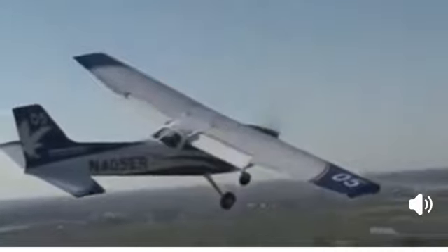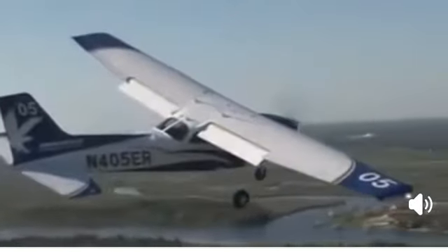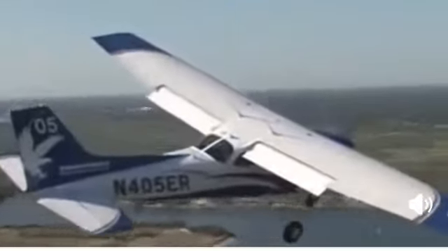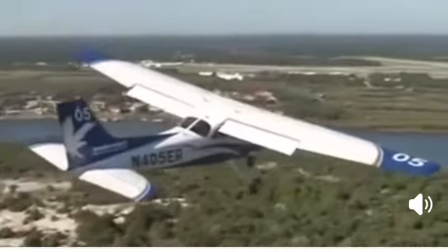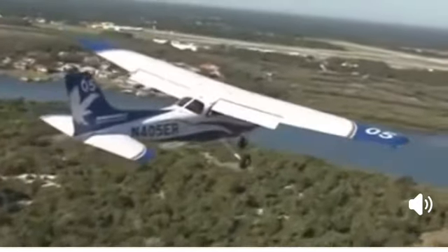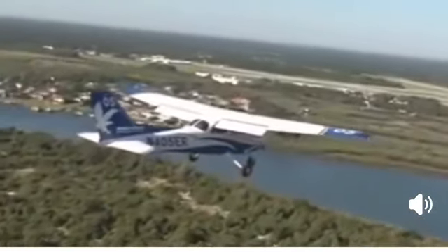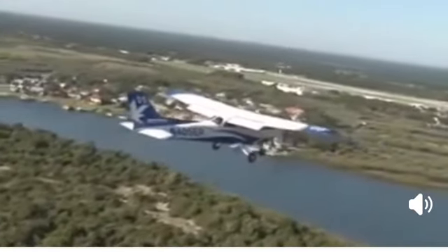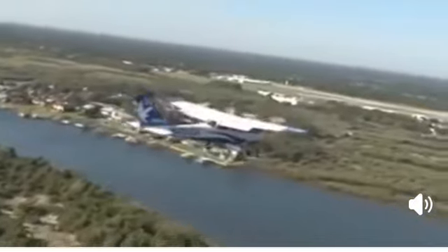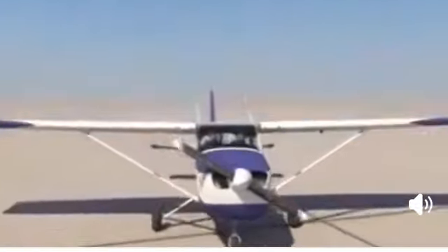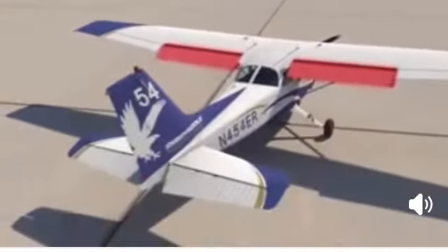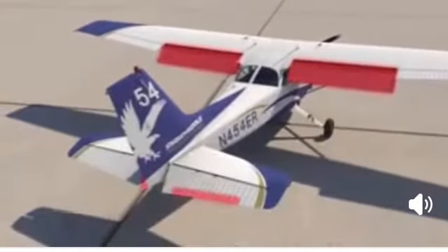The primary flight controls then fundamentally work the same. The pilot moves a control in the cockpit, which, through cables and other linkages, moves that control. As that control is moved, the airflow around it gets deflected, creating a force, and results in the airplane either rolling, pitching, or yawing. In order to help improve the performance of the airplane and make the pilot's job easier, most general aviation airplanes are equipped with flaps and trim, known as secondary flight controls.